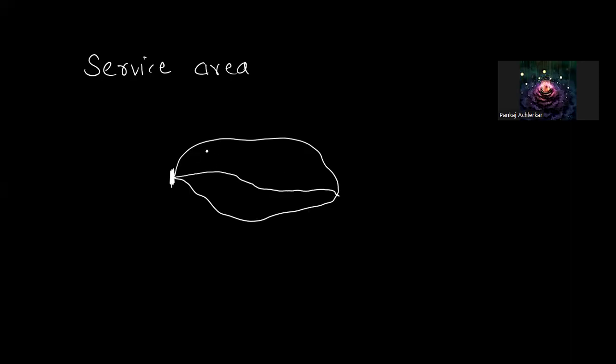And in this area, there are loads located at different locations, something like this. So in reality, the loads are distributed throughout the geographical area like this. So how does the individual load connect to the electricity coming from the substation? From the main feeder, some laterals are connected. Or we can call them service lines, and they serve the individual loads.